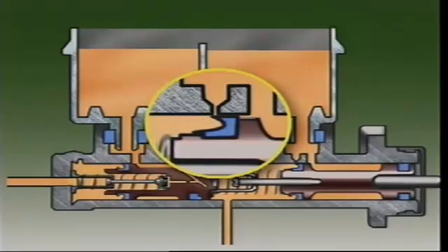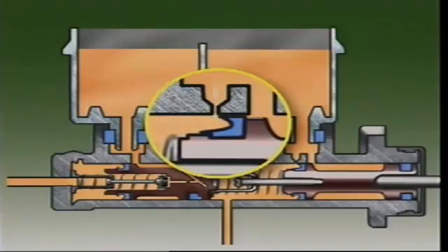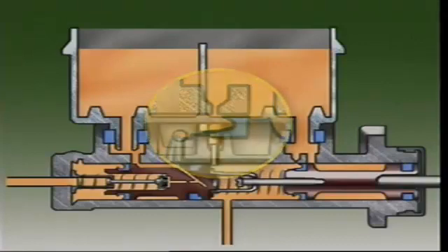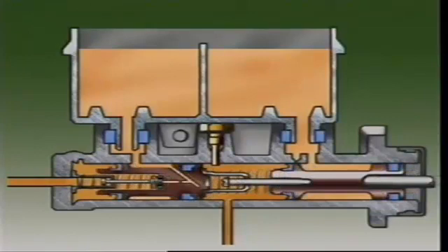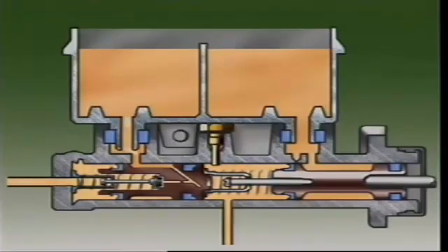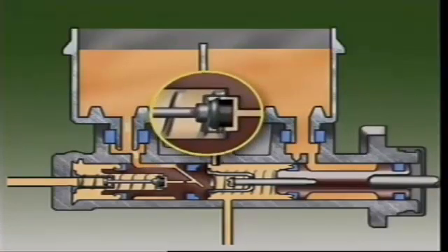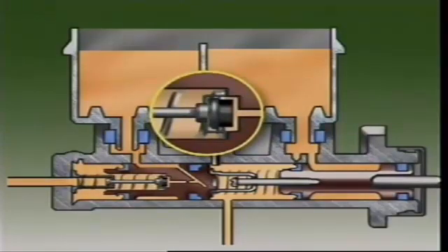When the primary piston is returned fully, any extra fluid coming back from the brake units displaces fluid into the reservoir through the compensating port. In the secondary circuit, fluid also at atmospheric pressure is forced back into the inlet port. The inlet port connects with the supply port drilling in the piston. Any difference in pressure lifts the center valve from its seat and lets fluid enter the chamber ahead of the secondary seal and prevents low pressures developing.